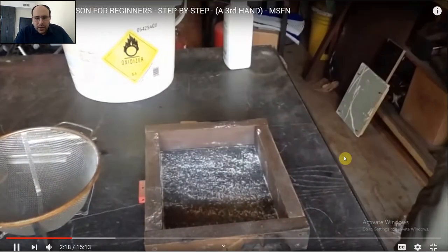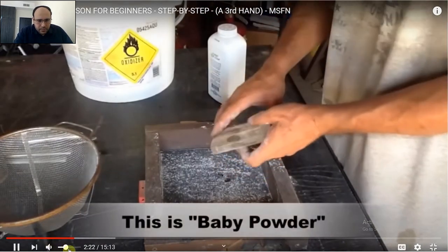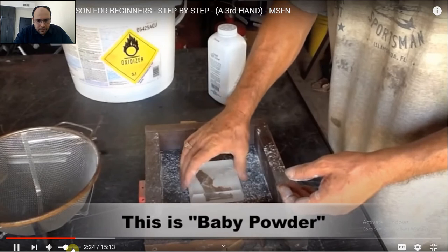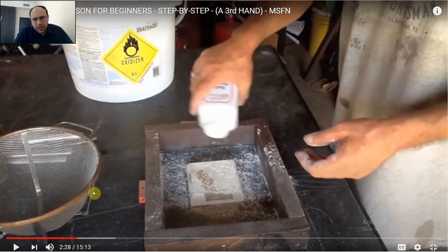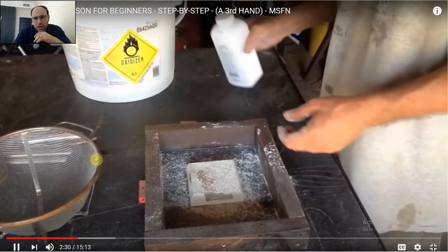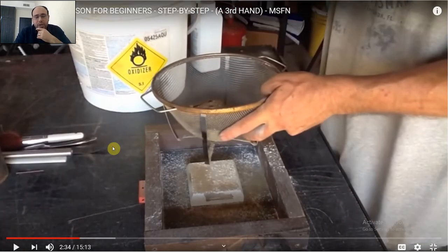Here I'm putting powder down to keep the sand from sticking to the table, and putting powder on the pattern to keep the sand from sticking to the pattern. Yeah, so he's putting this baby powder, which is available everywhere, just as he mentioned, so the sand does not stick to the table or to the pattern, so the pattern can be easily removed from the sand, as already shown here. So he's typically doing the procedure of the mold making.